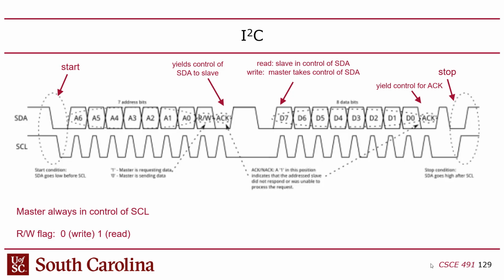You set up your data, and this could either be the master side or the slave side, whoever's setting the data. But someone's going to set the data up. And once the data is established, you bring the clock high and then low. And then you don't want to change the data until after the clock goes low.